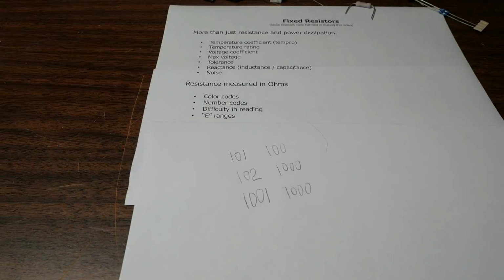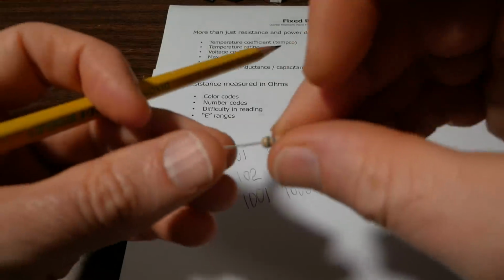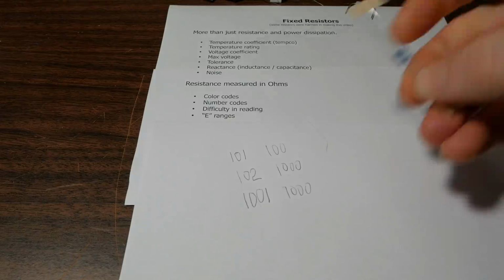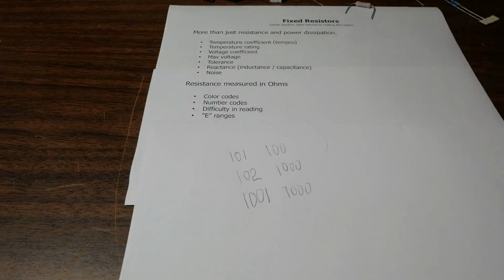The point I'm making, if you're used to the normal 3-band plus the tolerance band type resistors, like this one here, and you go grab a precision resistor, you think, well, right off the top of your head, you're thinking brown, black, black, red would be 1K, but no, it's not. That's actually 10K. So you have to watch out for that.